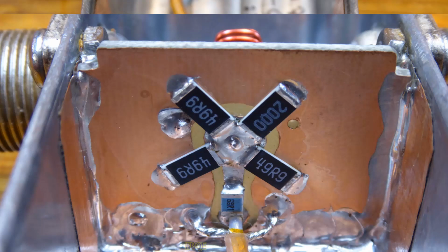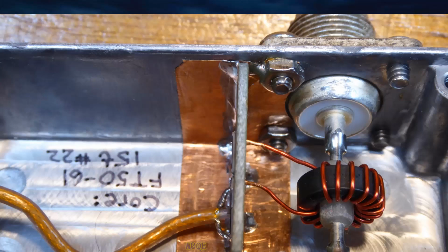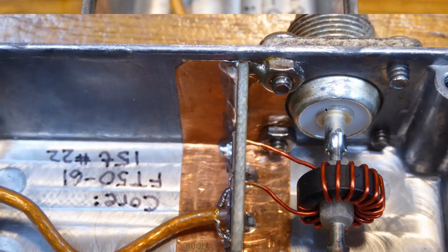And this circuit has worked pretty nicely. I built several of these. Here's a little bit bigger picture of it. When I built this box, I took a piece of copper tape, bent it down around the sides, burnished it down real nicely. This is a single-sided circuit board that's soldered along the edge here, so it has very good connection to ground. And then I put nuts here, and I soldered the nuts to this, so they have very good connection to the ground here. And this circuit has worked very, very nicely.